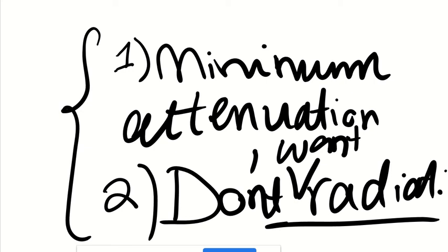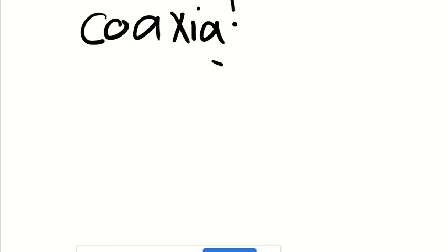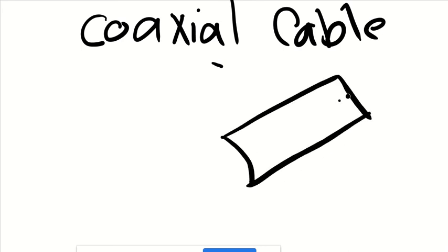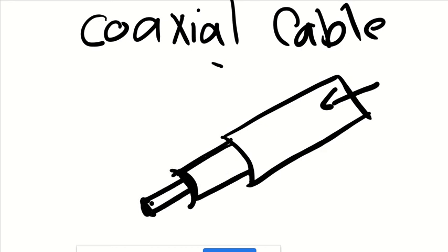And I'm sure all of you have seen coaxial cables. They're everywhere, even at home. I'm going to try to draw it. There are different types of transmission line. One of the most popular ones that we have around is the coaxial cable. A coaxial cable has an outer plastic insulation, and then another Teflon plastic insulation, and then you have copper here. They're widely used.